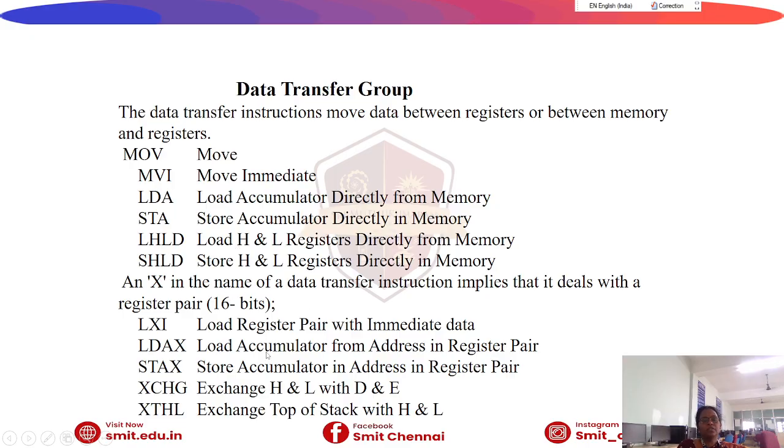Also, this is for 8-bit and similarly for 16-bit, that is expressed by the letter X. As the name of the data transfer instruction implies, it deals with a register pair, that is nothing but 16-bit. So here, when this X is present, it directly says that this is 16-bit data. For 16-bit, that is for a register pair, we have LXI, LDAX, STAX. Here STAX is store accumulator indirectly in memory. Similarly, there are others for 16-bit, or otherwise for a register pair.